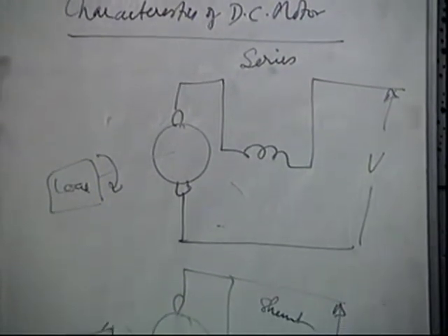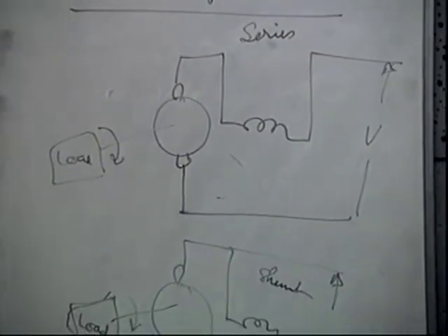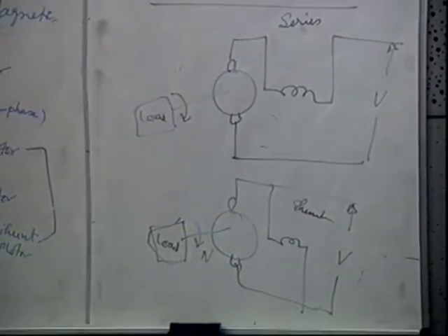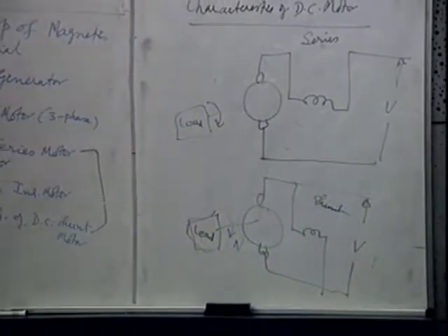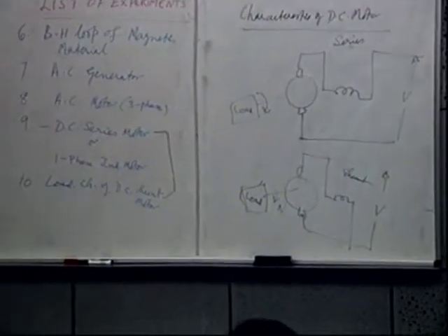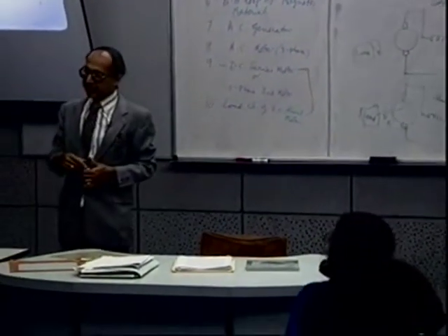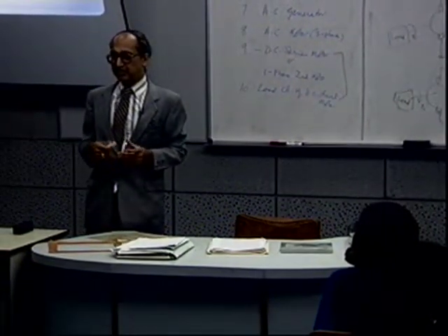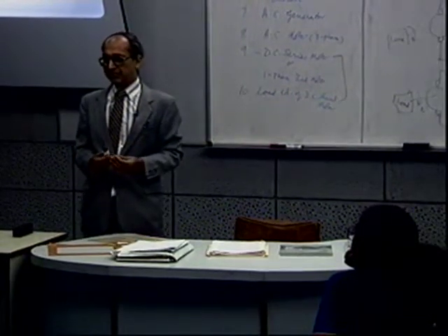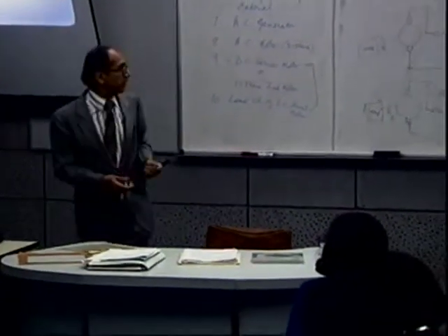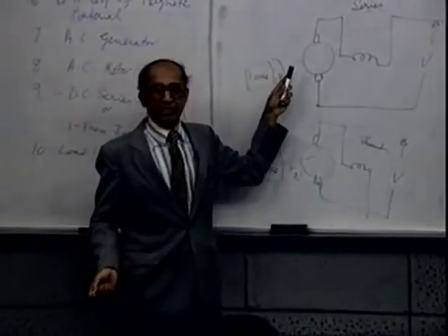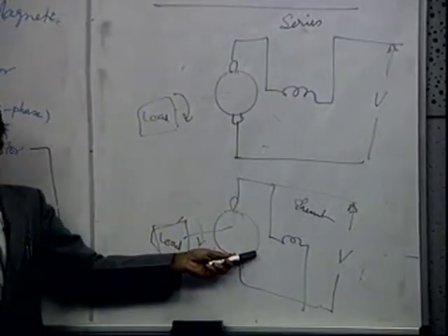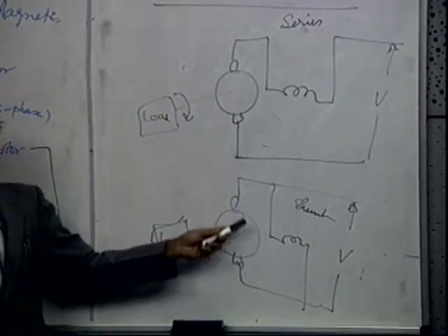Do we use three-phase induction motor in the trains? That is a recent trend. Recent trend is to have three-phase induction motors, because that is now possible with electronic control. You can have a desired characteristic of a DC series motor. The recent trend is to go for variable speed three-phase induction motors. So that's why it is expected that some of these motors may have reduced applications. Shunt motors are normally constant speed motors. They have two different characteristics.